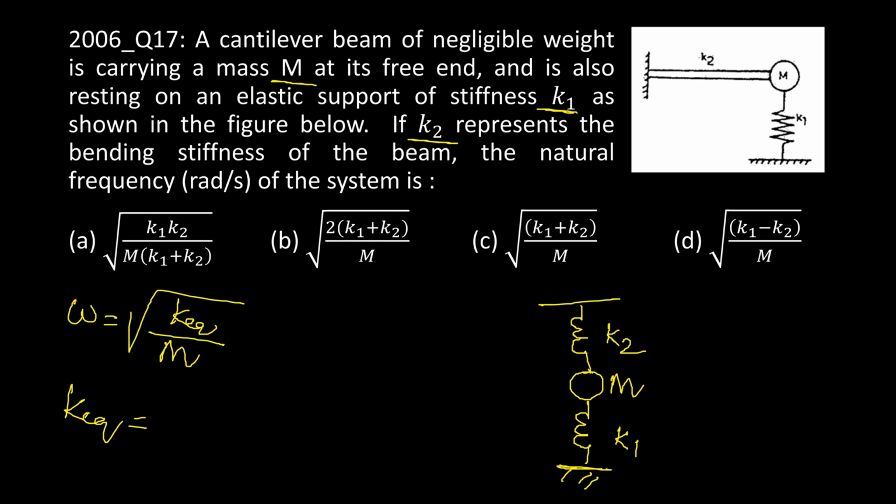So this system is clearly a parallel arrangement of spring mass system because mass m is supported by both the springs having stiffness K1, K2, and the deflection in both the springs is equal to delta, that is delta 1 is equal to delta 2, because the elongation in the spring having stiffness K2 is equal to the compression in the spring having stiffness K1.